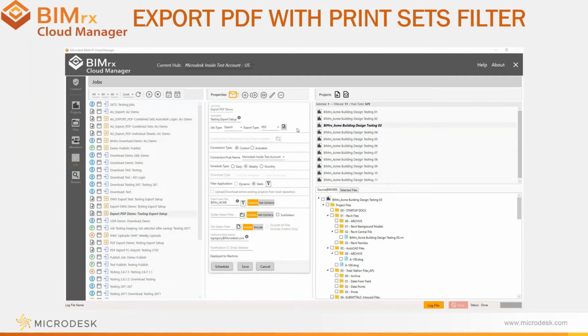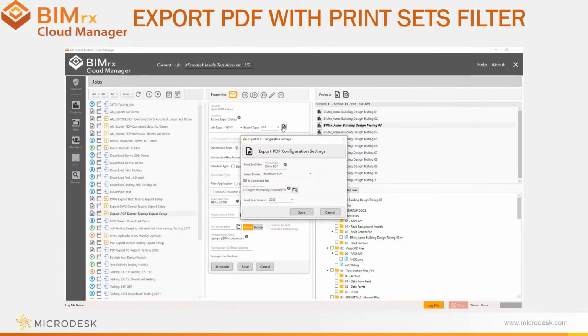Let's take a look at the new Export PDF print set filter in action. I've created an export PDF job, and we can find the print set filter in the PDF export settings. A Revit print set filter now enables control over which print sets are exported across multiple models and projects at the same time. If a print set name contains what I put in the filter here, it will be included